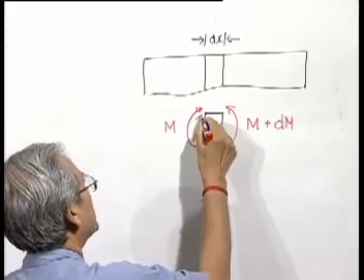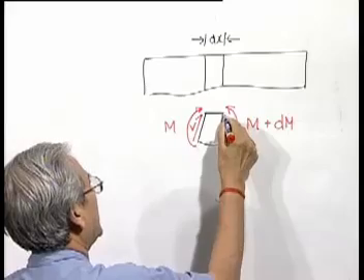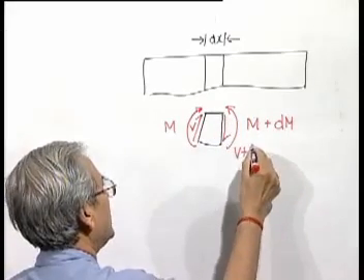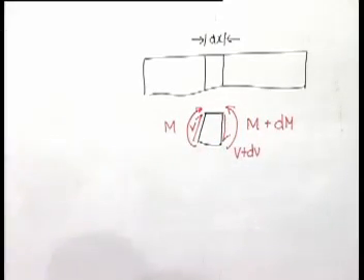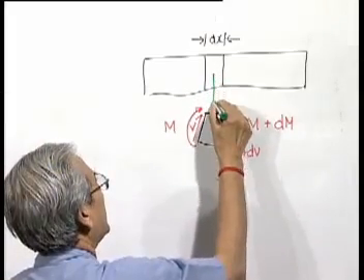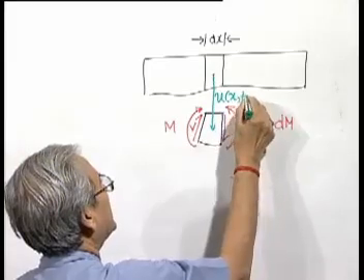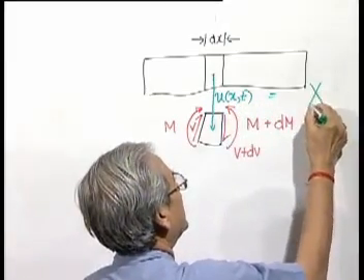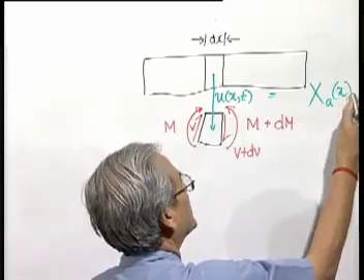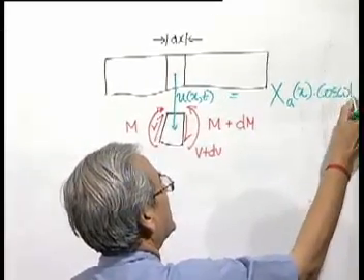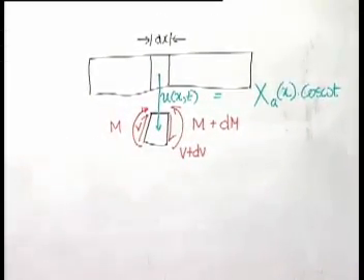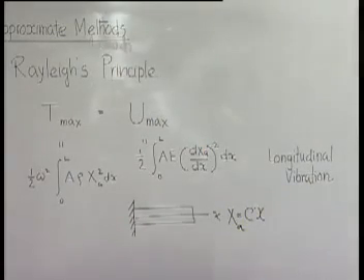The force is here, say for example V, and here again it is V plus dV, resultant force is also very small, and the displacement of this from here to here is given by u, which is a function of x and t, but which we write as a function of x and cosine omega t. We assume this normal mode oscillation to derive the Rayleigh's quotient.